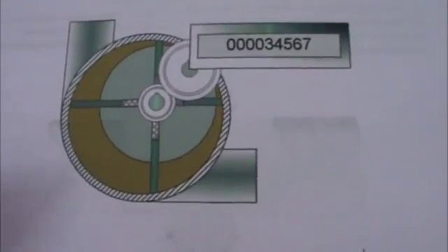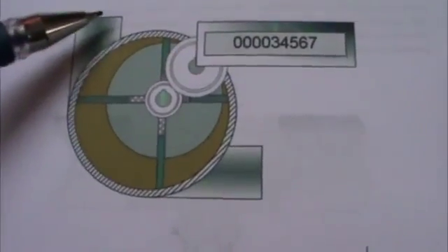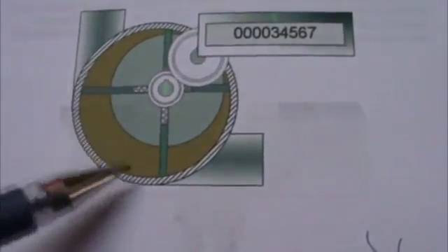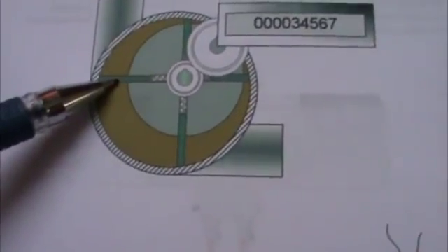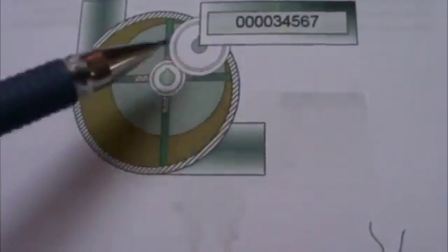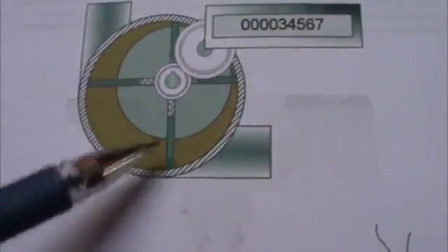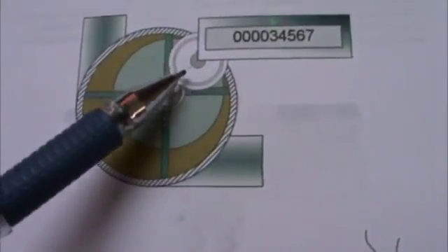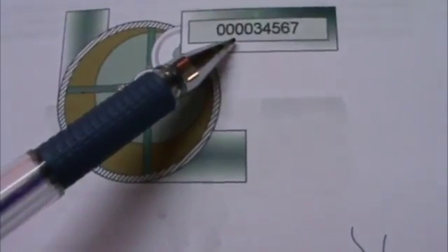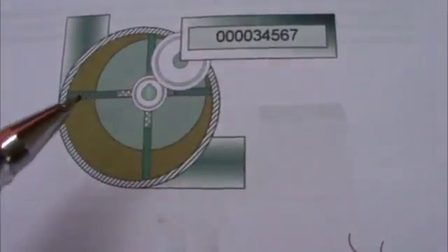This is a typical vane type flow meter. The fuel oil enters the flow meter in this direction and goes out through this. As it enters, it starts to rotate these vane blades. The vane blades are located here, and there is a smaller gear over here. As the fuel oil goes this way, it rotates the vanes, and this gear engages with this, and this gear starts to rotate. The number of rotations this gear makes is recorded over here and indicated as the mass flow rate of fuel oil. This type of flow meter is found in most of the ships.